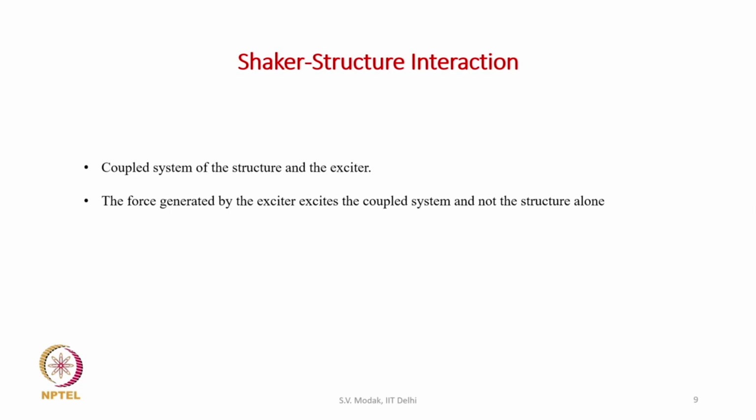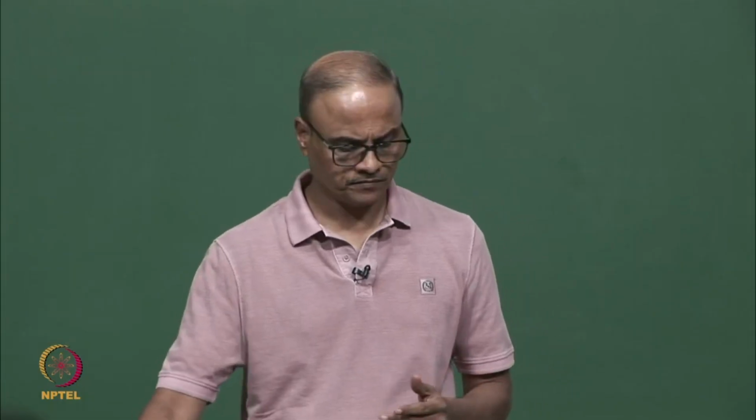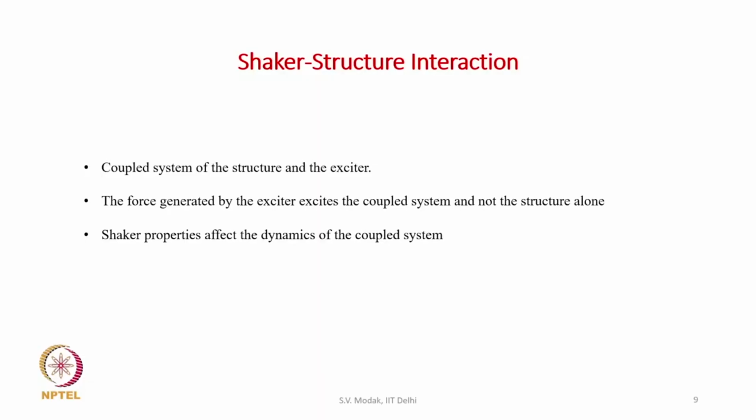Another thing is that the force generated by the shaker vibrates not only the structure but also the shaker mechanical system. So the generated force is shared by the structure and the shaker, and therefore the shaker properties also affect the way this force is shared. Therefore, by analysis of the interaction between the shaker and structure, we would like to figure out what measurements we need to take in order to identify the dynamic characteristics of the structure.